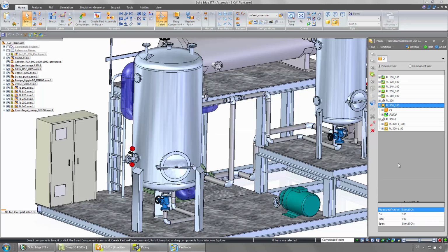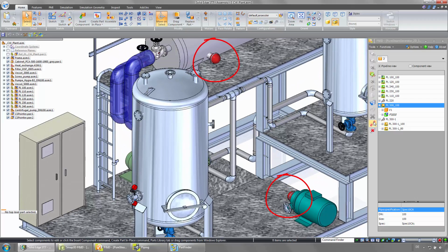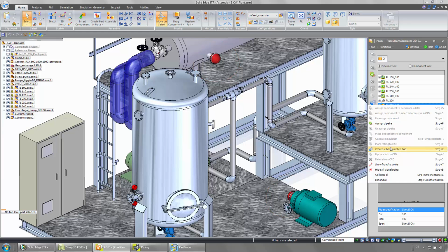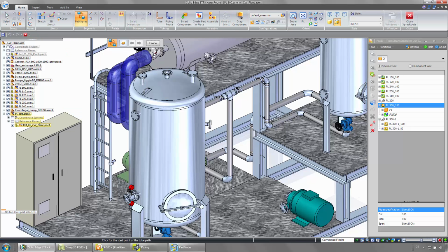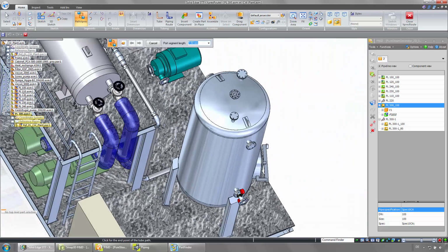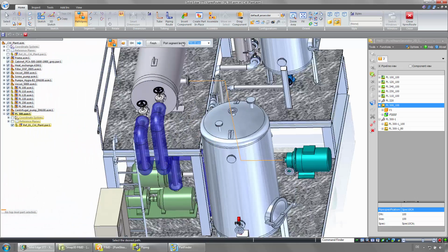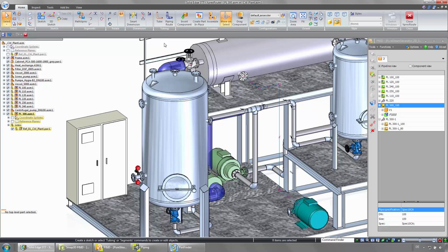With the information from the P&ID, the 3D pipes are ready to be created. The function FromToPoints helps the user find the correct connection points. After a subassembly is automatically created, we draw a 3D pipeline path with the Solid Edge Express Route function, Path Express. To draw customized lines, just choose the Line Segment function.